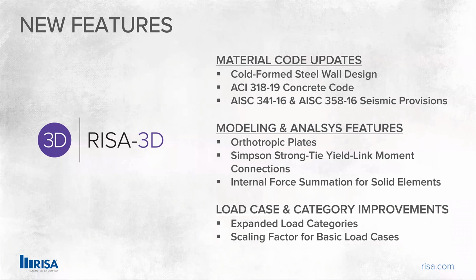From a modeling and analysis standpoint, we've added a few really nice features. One that I'm really excited about is orthotropic plates, giving you the ability to get different stiffness in different directions for plates. We've also worked really closely with the people over at Simpson Strong-Tie to add the Yield-Link moment connections. We'll be able to spec those out in the pinned releases or end release conditions in a RISA 3D model. Finally, we've also added some internal force estimation tool elements for solids. Additionally, we've expanded load categories, so you can now add up to 100 other load categories. That was a really highly requested feature. And we've also added the scaling factor for basic load cases.